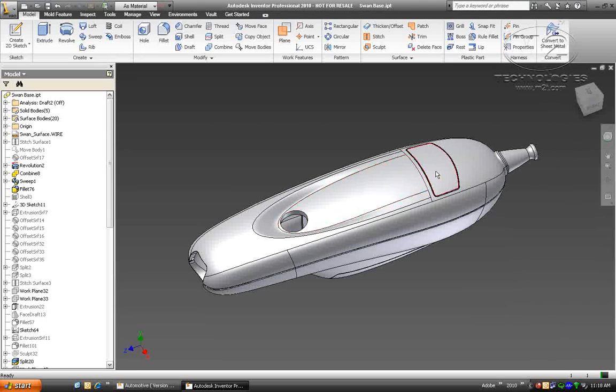Now, if you take a look at this display area, there was a change that required this recess to be pushed forward and the display itself to be pushed forward by 300 thousandths. So in essence, we need to get rid of this surface, and since this split was already in here, add a patch, a new surface through here. So in Alias, we'll go ahead and make that change. And I'll show you the original file that we started with, and then the final file that is then going to be able to update this.